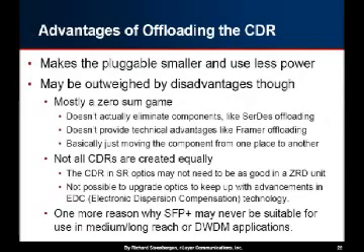The other kind of evolution that you see on these optics is more and more offloading of the optics to make them smaller and use less power. The new one that's come up with SFP Plus is to offload the CDR. The only advantage of this is, yes, it does make the pluggable smaller and it uses less power, but it actually has a lot of disadvantages as well. At the end of the day, you're not actually removing any components, and you're not really optimizing any components. You're just kind of moving them around. So yes, you've made the pluggables take less power, but you've just moved it to the board. So it doesn't really help that much.